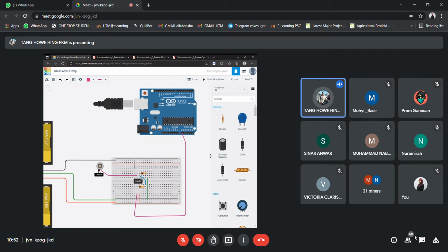Okay, as for this photodiode, one thing we need to know is that this cathode needs to be connected to the reference, so that it is part of the system, and therefore we just connect it to this ground. Okay. All right, so far so good. Is everyone clear about it? Clear about these connections?